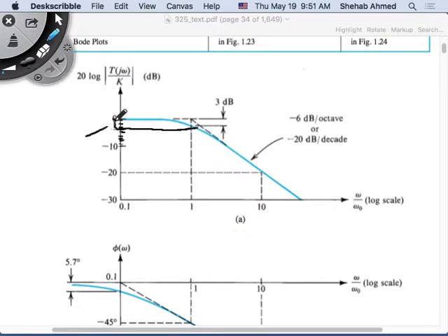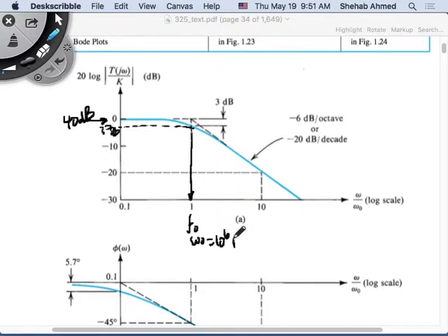But you will have to plug in your proper values. So plug in values for your circuit. In your circuit, your DC gain was 40 dB for the circuit that we came up with now. So what is this point? 37 dB. Where is this occurring? At F naught or omega naught, which is 10 to the 6 radian per second. What is the slope of this? It's always going to be minus 20 dB per decade.